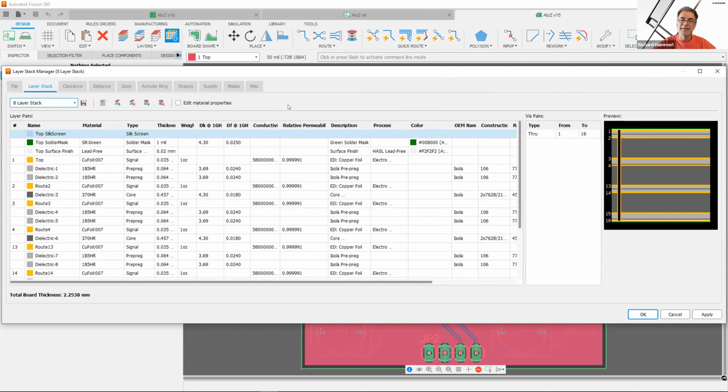Yeah, that's really good advice. Talk to your service before you start to create the board if you're unsure what to do. Yeah, and even if you know what you're doing, it's still a good idea. I know in mechanical circles it's basically design whatever you need and then find somebody who can make it. But in the case of electronics, it works the other way around. You're better off finding a manufacturer, figuring out what they can do, and then trying to conform to that. Because otherwise, like Richard said, you might design something that nobody can build, and then you have to do all that work over again, so you will have spent double the money in designing it.